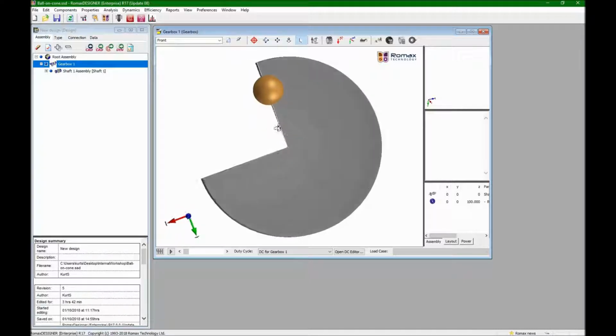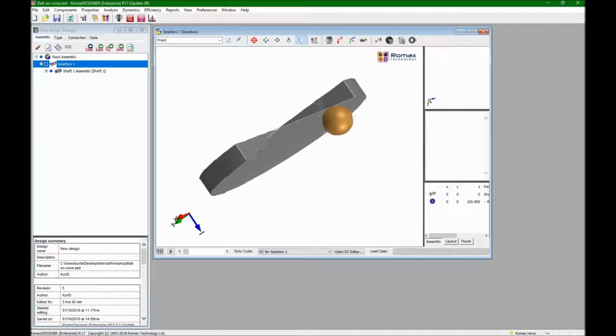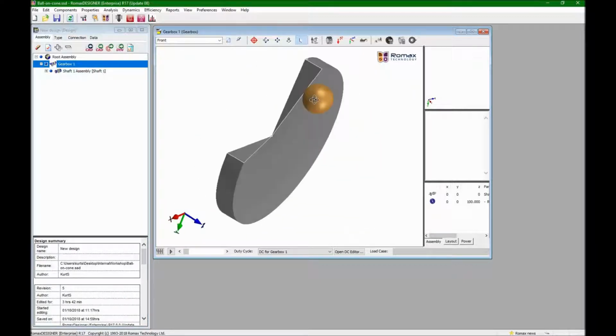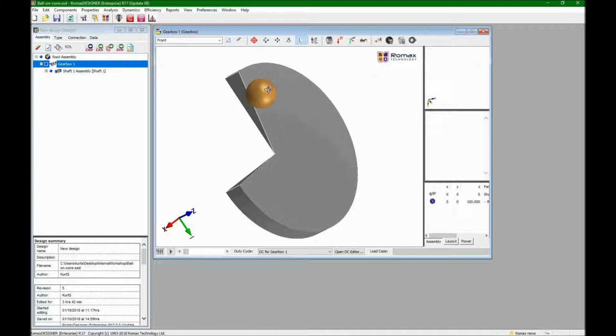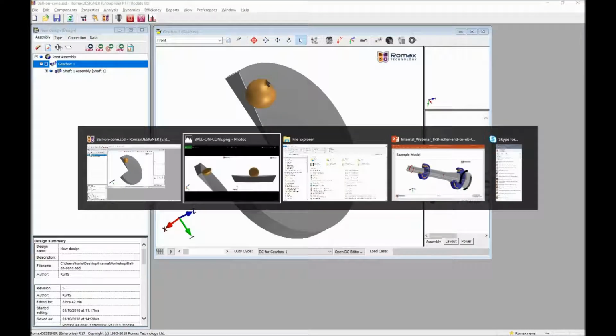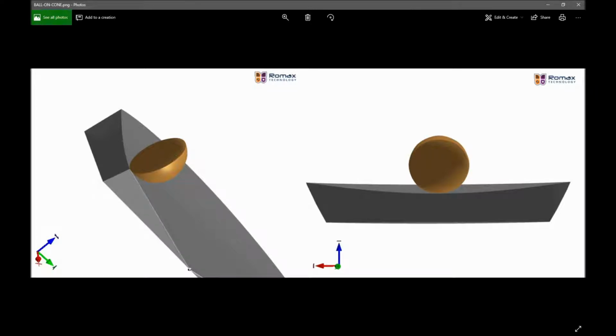And when you do the stress analysis, you have to put two planes through the line of contact. Now that's a bit of an angle rather than horizontal. It's a bit of a down angle. But radially, it's a straight line on the ball radius, and then when I go 90 degrees to that, it's the ball radius, and that's where my picture comes in. When I go across the race, you see cut through that ball, it's a very large radius. Now it's probably more of an elliptical surface. I really didn't run any numbers on it. I was just trying to make sure I knew what it looked like. So as long as I can figure out what the curvature is in this very small area, for practical purposes, that's a radius.